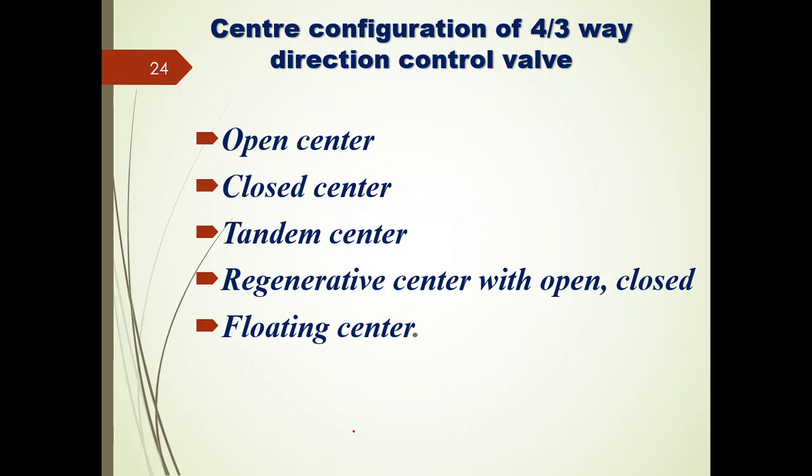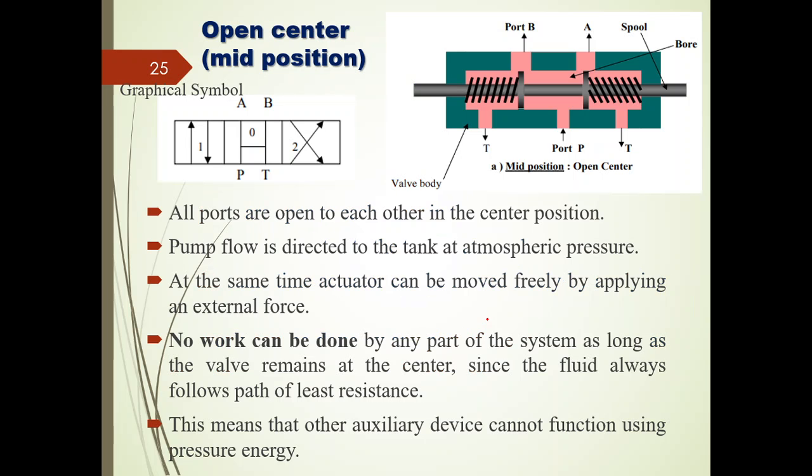Depending upon the various configurations of this 4 by 3 direction control valve, I can classify it as open center, closed center, tandem center, regenerative center, as well as floating center. Let us see these one by one. So this is the pictorial representation, and this is the graphical symbol of a 4 by 3 direction control valve, which is of open center, right?